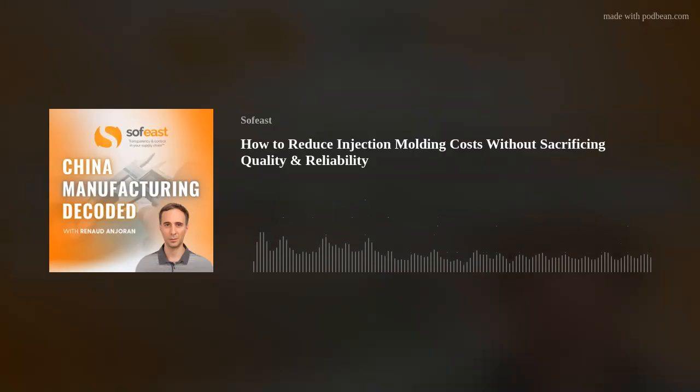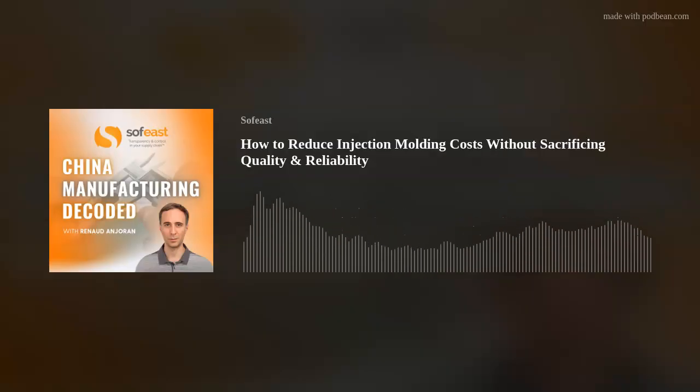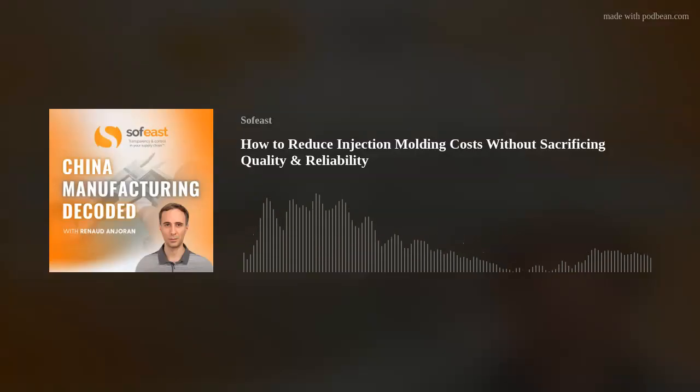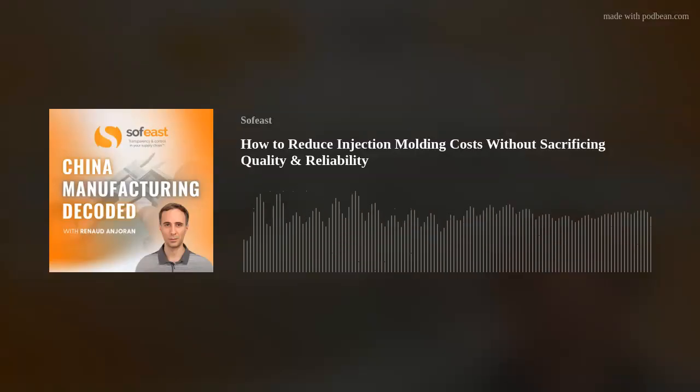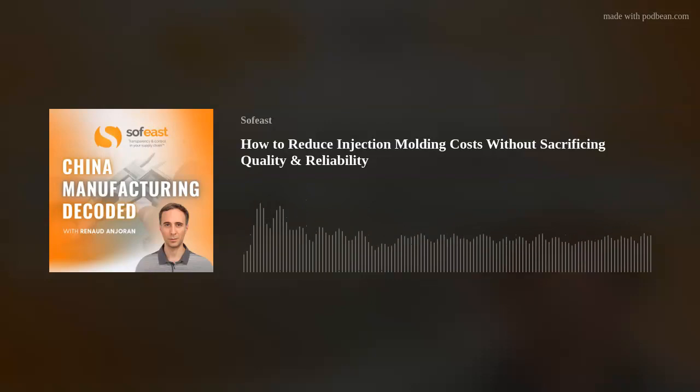Processing materials. I like closed loop systems. I like SPCs on critical to quality, control charts. Make sure the machine is running totally optimized. Make sure you've got sensors all over the tool in order to allow the molder to make sure that you're running at an optimum level. This way is very, very efficient. You're going to get a high yield from your part. So all of the costs are going to balance out from a part point of view. Your yield rate is going to go up. So this is another process improvement for running your injection mold tools.